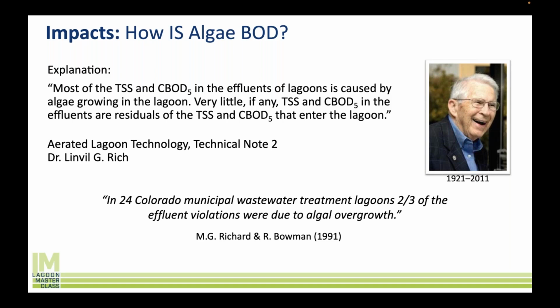So it's not that the lagoon is failing to treat the influent constituents of BOD and TSS. It's that it is doing a great job of treating that, but it's helping algae grow, and then those algae are then showing up as BOD and TSS in your effluent sampling.